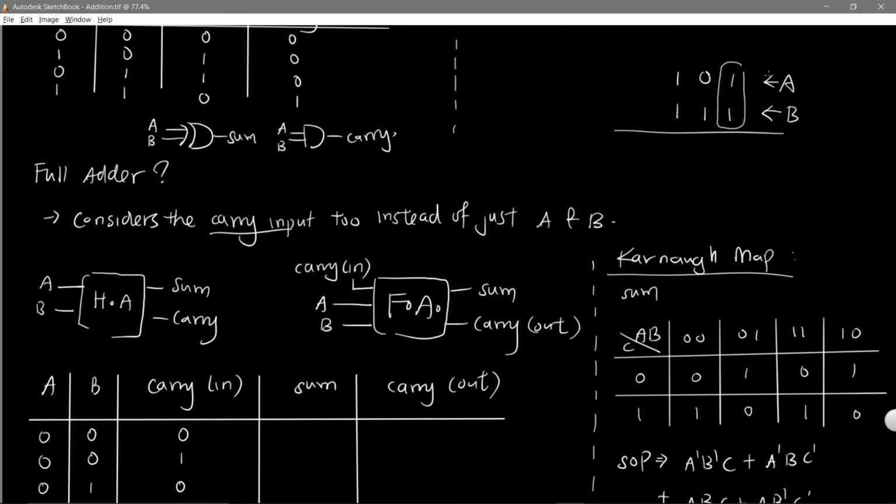And then you don't have any carry values here, so the carry at this bit is 0. But then if you sum this, it will carry 1 to this place, and the sum here will be 0. And now you have a carry of 1 at this bit. So a carry of 1 means that this carry input is 1 now. And A is 0, B is 1.